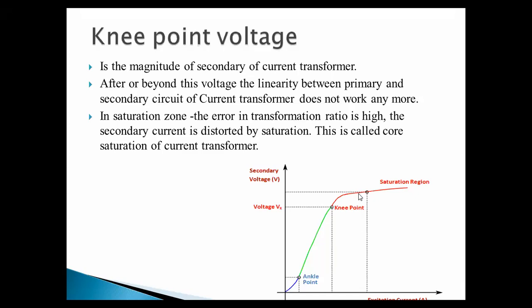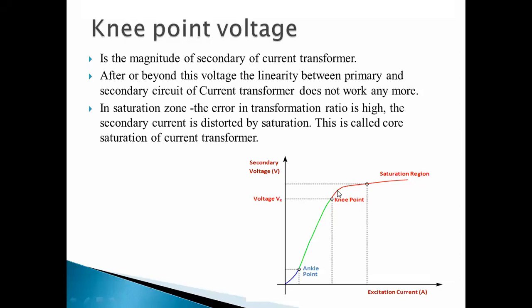There is a linear characteristic between this voltage and current, but after saturation, if you increase that current, the voltage remains constant, and the point at which it stops increasing is nothing but your knee point.